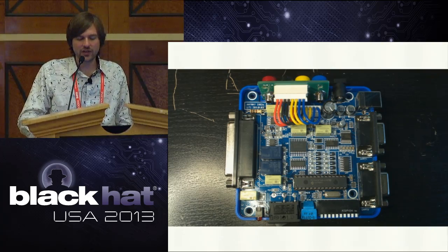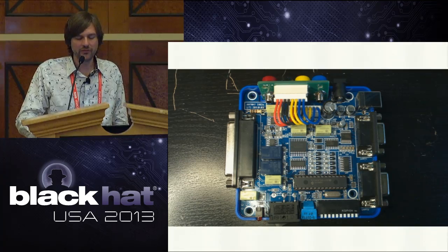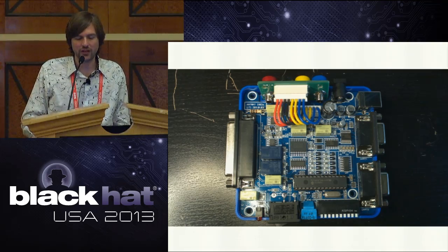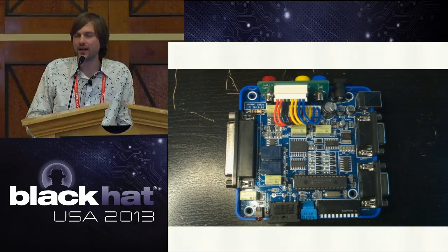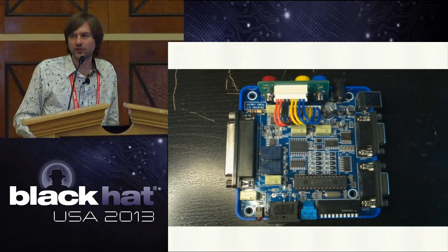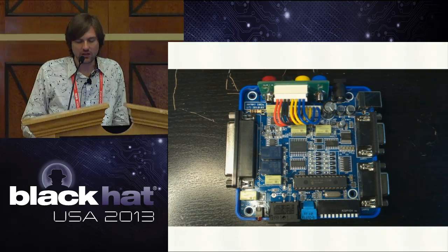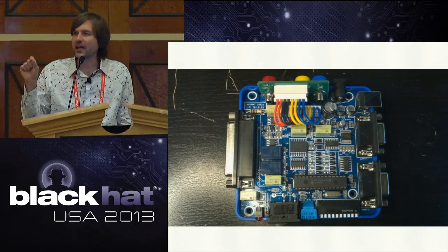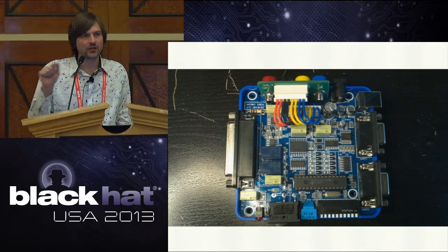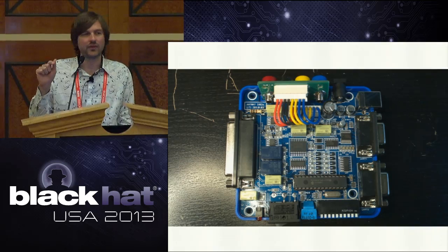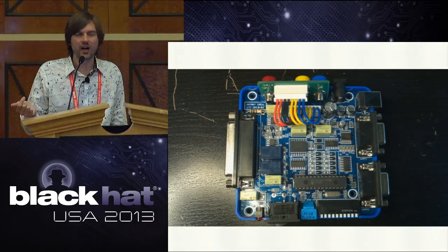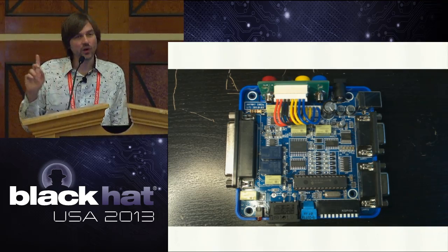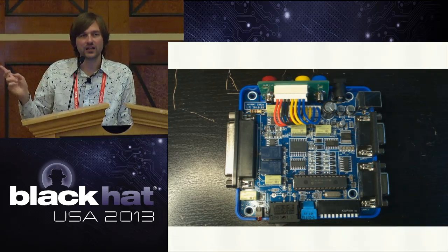And then there's this grid just above that long DIP package microcontroller. There's a grid of surface mount parts that includes a bunch of fixed resistors. You can't read it from there, but with my magnifying glass, I could read the values off those resistors. And sure enough, there were several values that corresponded to the table of values that are commonly used for those multiplexer ICs. Interestingly, 150 kiloohm is not in this.